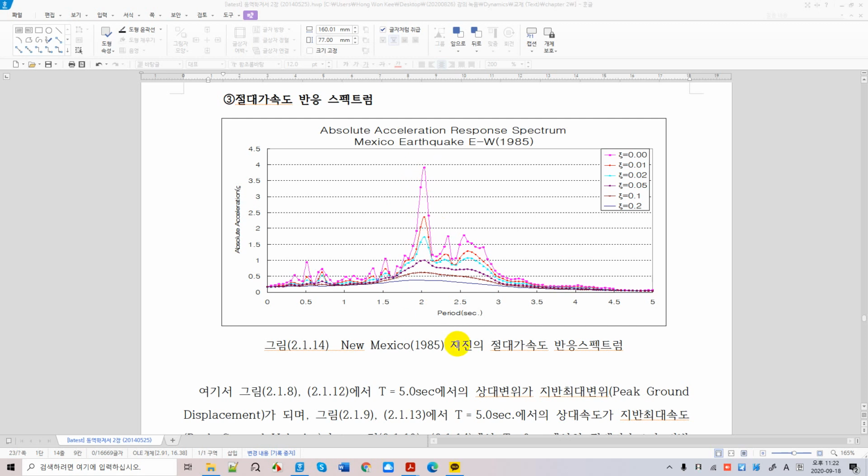Why does a 20-story building get damaged? If you remember, the formula that I gave you was T = 0.1 N, where N is the number of stories. So N is 20, which is a 20-story building. What period do you get? You get 2 seconds, right?